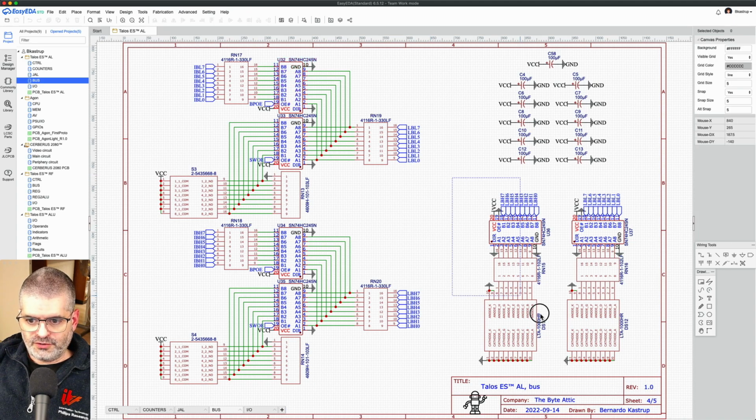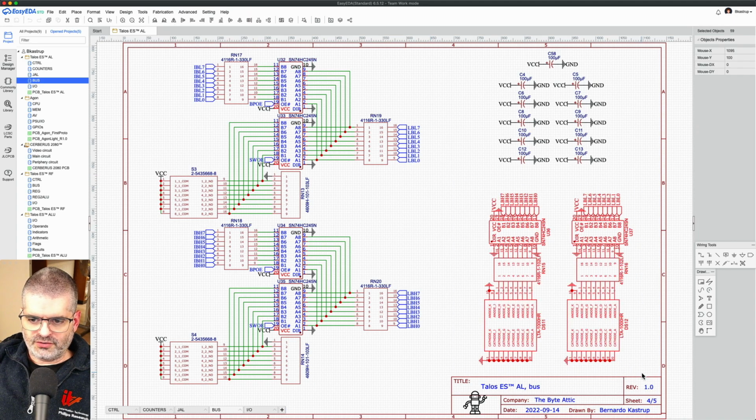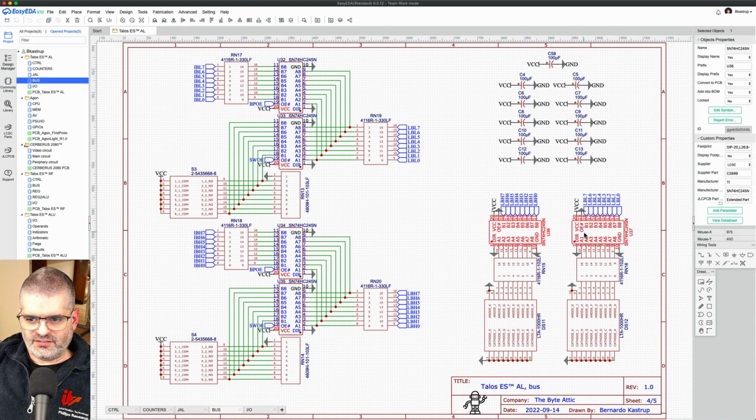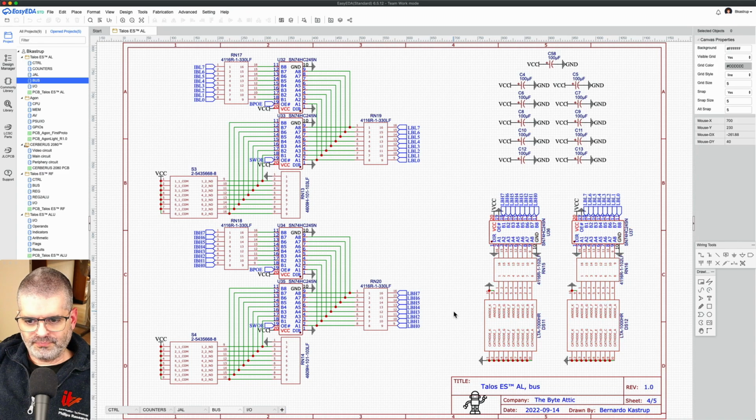And then we want to visualize what is on the local bus. And for that we use, again, separate buffers, in series resistor arrays for current limitation, and two LED bars, because we are talking about 16 bits here. And then there was a little bit of space, so I put the decoupling capacitors there. I think this time I'm using 11 decoupling capacitors.